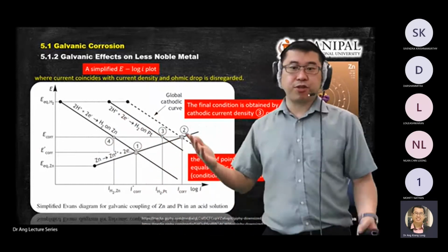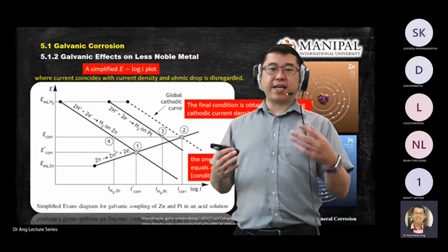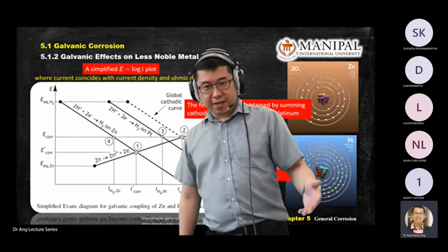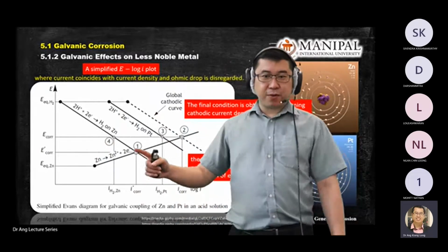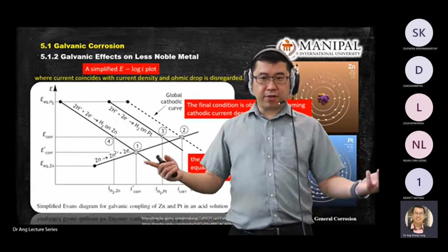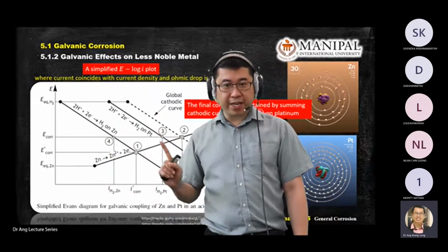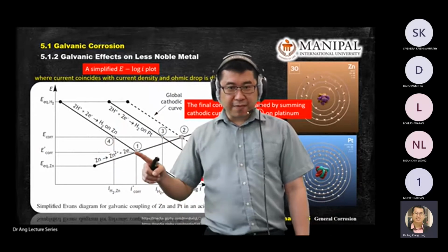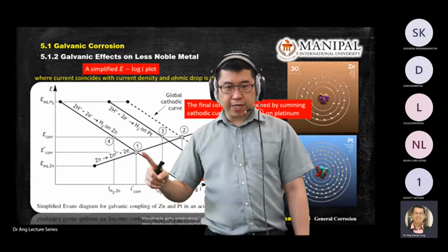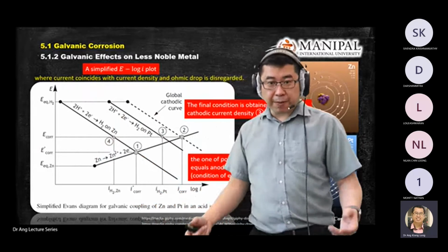So on your graph, you have 3 lines, and then identify the point before coupling. What is the value before coupling? It is 0.1. Label 0.1 on your anodic process, any point, any location, it doesn't matter. You just pick one point along this line and project down, and label it as the corrosion rate before coupling.